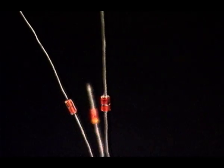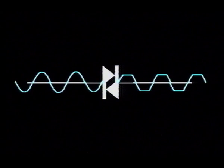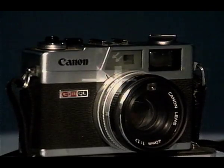Then there are diodes used in the AC power regulation circuits like SMPS of a color television. They are like two Zener diodes connected in parallel, opposed to each other. They can regulate AC just as the Zener diodes regulate DC. Here you see a photodiode. It is used to detect and measure light, for example, in a camera.